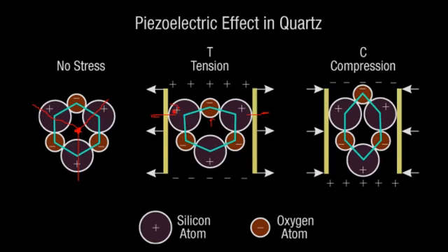So you can think something like this. You have a charge here, and this is your state of center of charge, so that will be a little higher when compared to the first image. Similarly, when you compress it, what happens? Your positive charges will be compressed like this, and this positive atom will be moving downwards. Hence your center of charge will be shifted downwards, so that your net positive charge will be at the bottom surface and your net negative charge will be at the top surface.